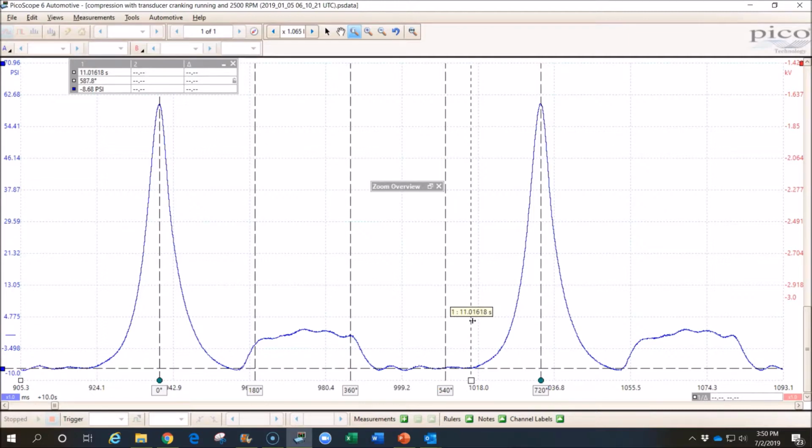So just as a reminder on valve event timing, this is the point we can see when the exhaust valve opens, and that's very clear and defined. This is the point where the intake valve closes. That's very clear and defined. Where the exhaust valve closes and where the intake valve opens, it's a little bit harder to see in here. We don't know that exactly sometimes. Usually there is an overlap because this is the point where the intake valve opens, and somewhere in here is where the exhaust valve closes, and that area would be called the valve overlap.